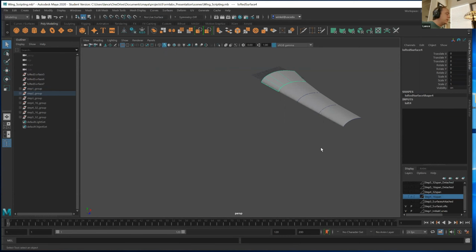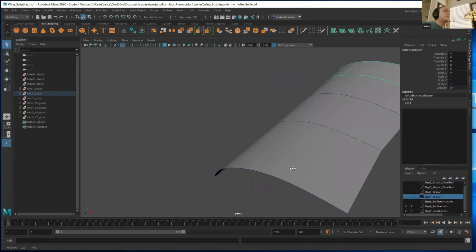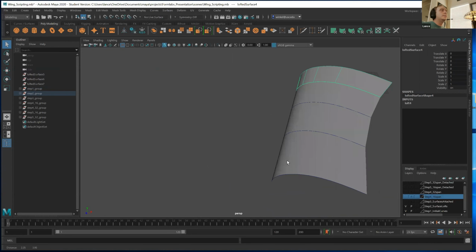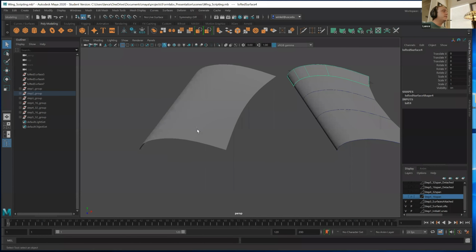Now, they look pretty clean. The nice part about anything that is based in a curve-based media, just like CAD, is that NURBS is only tessellated, turned into triangles, when you render it like we do here on the stage, or when you export it to a polygon or to an STL. Okay. Now, I took those surfaces and I attached them.